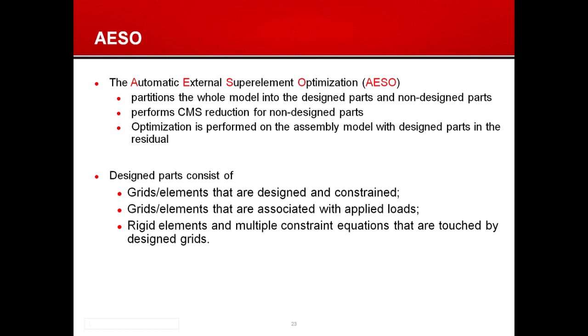But the user doesn't have to be familiar with that at all to be able to use this functionality, because what Nastran would do is put all the non-design components in the external superelement and reduce that, and keep the design components in the residual to be solved for.